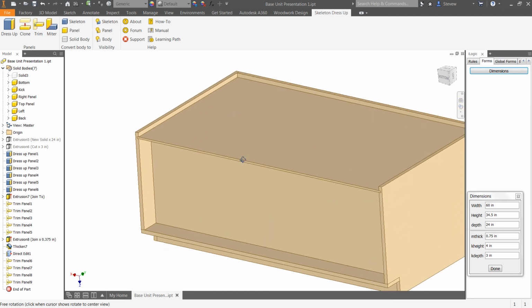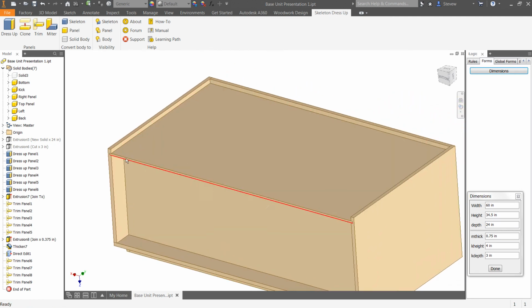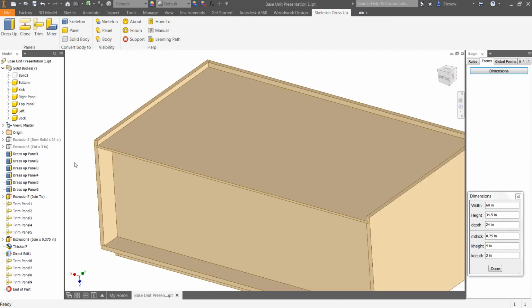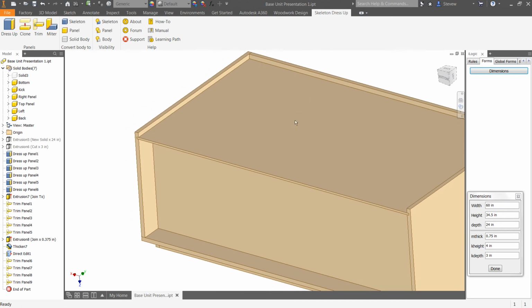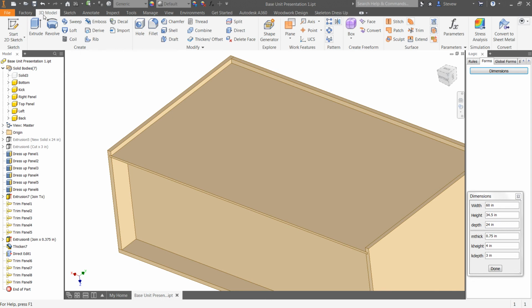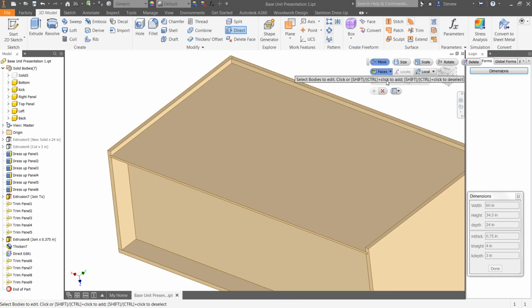Now, the next thing is, it wasn't absolutely necessary for me to cut that 3/8 inch off the bottom, because maybe the back won't go all the way to the bottom. It'll go to the bottom of the surface that's here. So the direct editing tool, completely your control. If I say direct edit, and I say not a solid, but I say face instead, so I can move solids or I can move faces.